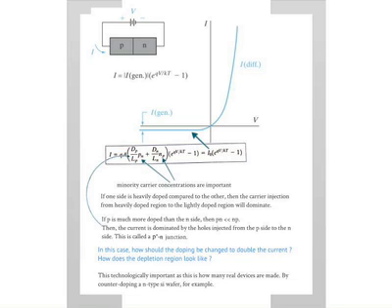In other words, if you have one side heavily doped and another side lightly doped, and you can control doping in order to increase current, the only control really that you have is the lightly doped side. So in order to, say, double the current, you would decrease the doping here by a factor of 2. It's a little bit counterintuitive. So think about this. Of course, Pn is the holes in the n-type material, and I need to double that basically. The current is proportional to that, because that term's gone away. So if I have to double that, what do I do? I dope the n-type less. I need more holes.